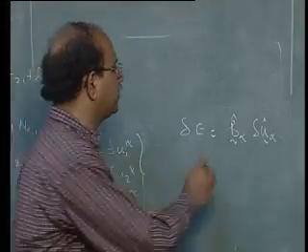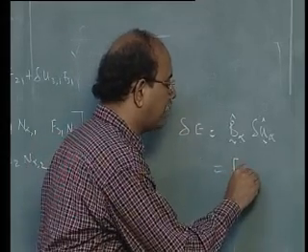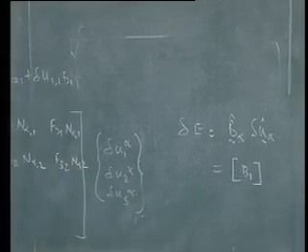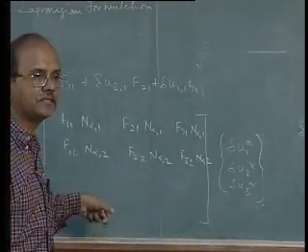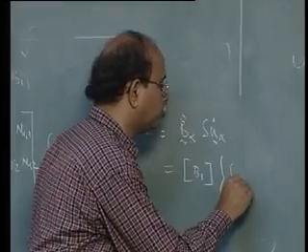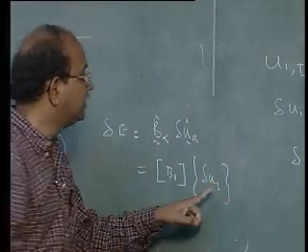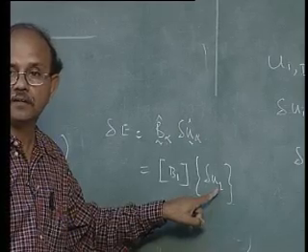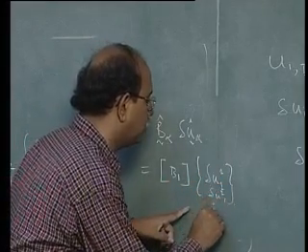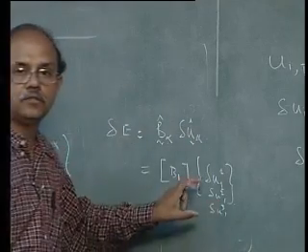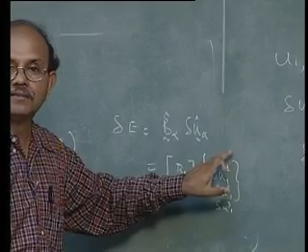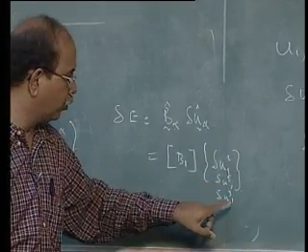So in other words, there will be a B1, where alpha is equal to 1 in all these places, B1 into delta U1. This one indicates this is a vector. So this will become 1, 2, 1, 3, 1. These will be the 3 entries for the 3 degrees of freedom of node 1.